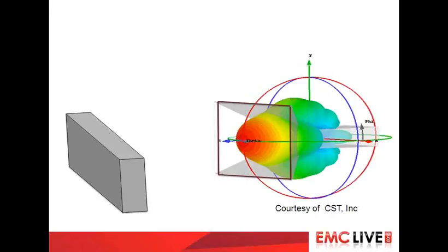When you had lower frequency testing, you had a lot of reflective power that the amplifier had to bear. But that wasn't because of what I just described, the reflection from the EUT. That was because the antenna was such a bad match. The RF power would travel from the amplifier along the cable, see the bad match at the antenna, and come thundering back towards the amplifier. Those days, thankfully, have gone, because above 1 gigahertz, with these antennas, you get far, far better matches. And so Mother Nature has taken that away from us.